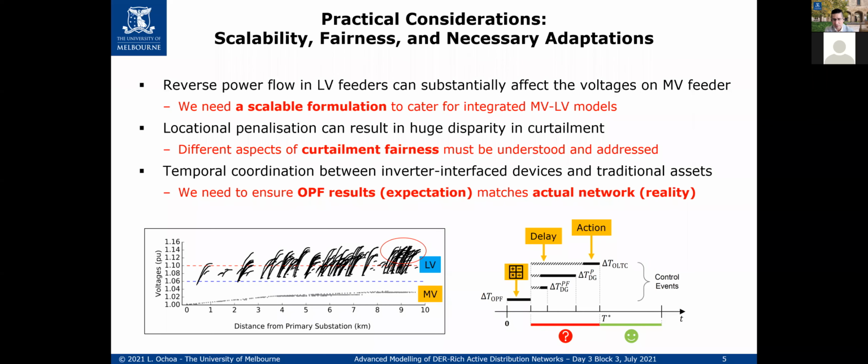We were talking a lot already about export limits, what will be the export limits that will keep the voltages within the limits, on the asset congestion, and the thermal utilization of the assets within the limits. Yes, we can calculate settings for all the different PV inverters or the charging of the batteries, whatever you want. But how do you differentiate the settings that you send to a house that is at the very end of a feeder and the house that is closer to a transformer?